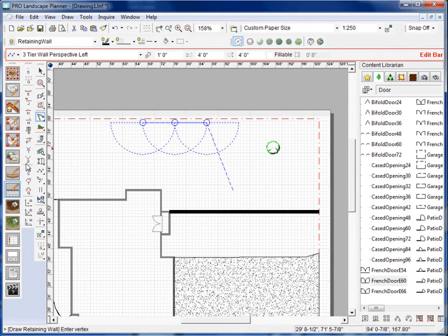Similar to the intersection snap is one called a two-point intersection, which is the number 2 on the keyboard. I'll click on the intersection snap tool, and I'll also select my foundation wall tool. Now the intersection snap gives me this little circle which wants me to choose a line to set as my intersection line. So if I click on this little short line on the side of the porch, it creates an imaginary dotted line there.